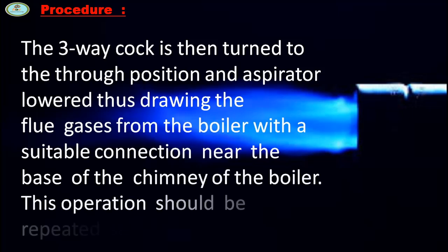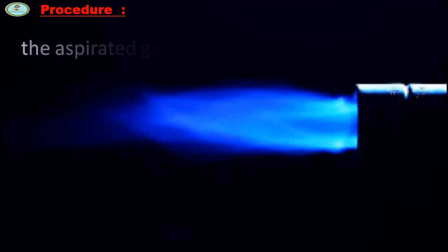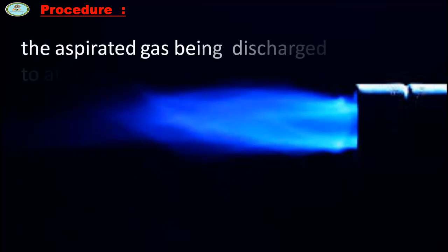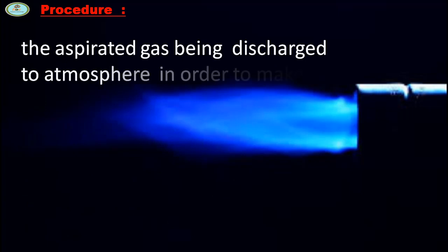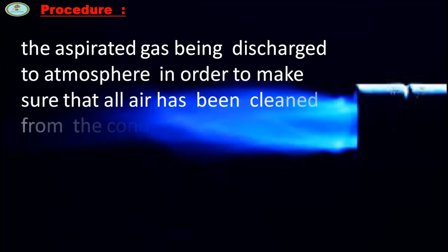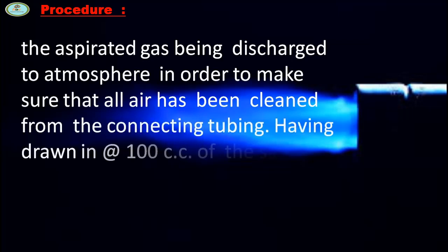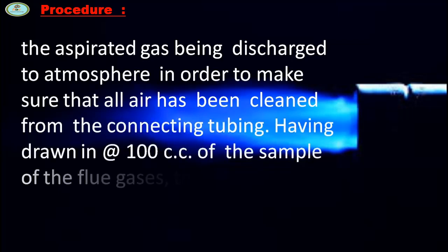The operation should be repeated several times, the aspirated gas being discharged to atmosphere in order to make sure that all air has been cleared from the connecting tube.